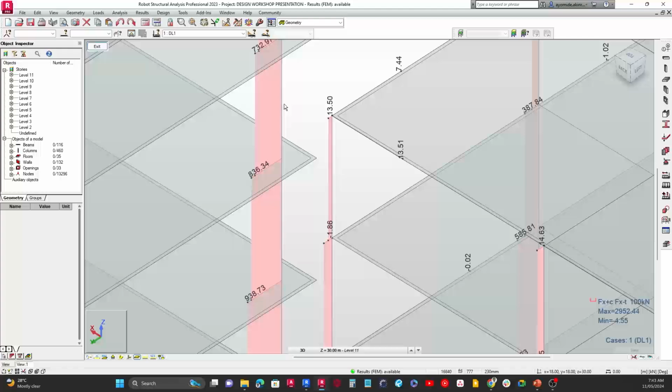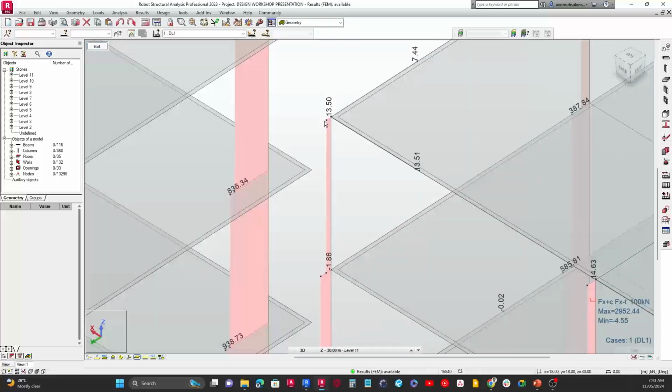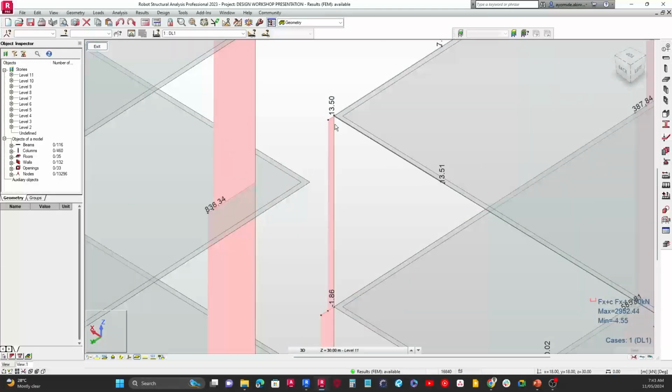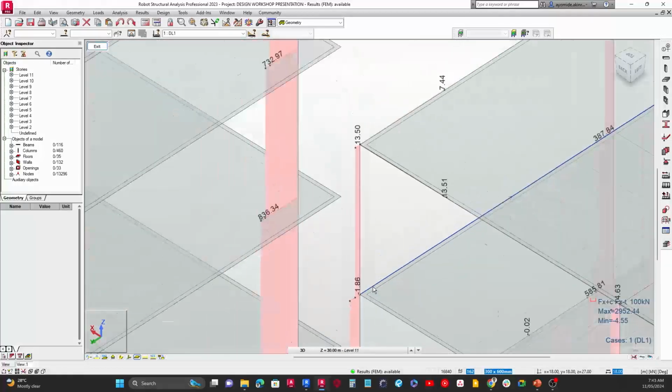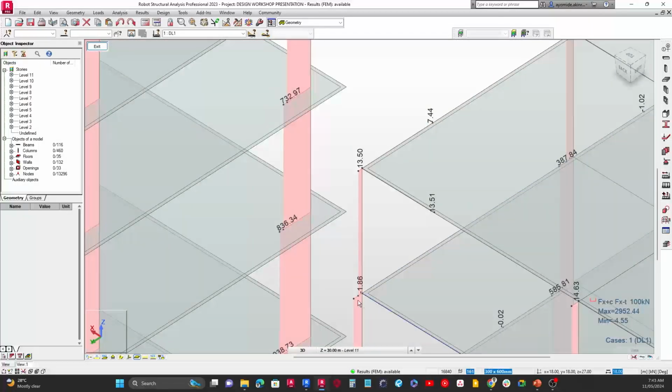All right, great. So we have about almost, this should actually be greater than this, but let's just look at the diagram. You can see that at this point here, just like we saw in the other application, the loads coming from this beam and this beam here add up and increase the axial force. But as we go over here and come down here, you can see that we have an increase. Now the reason why this increases is that at this floor as well, we also have loads coming from this beam and this beam. You can see that the axial force now becomes bigger.